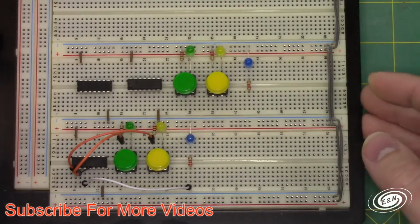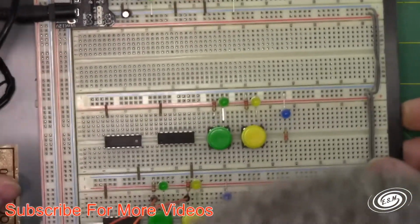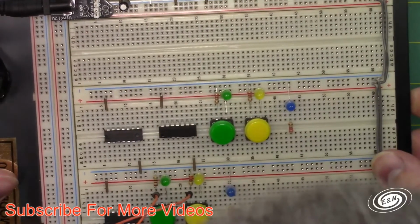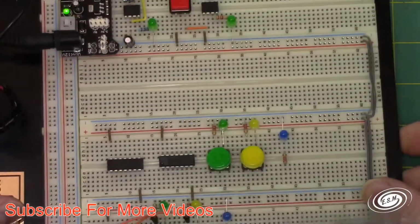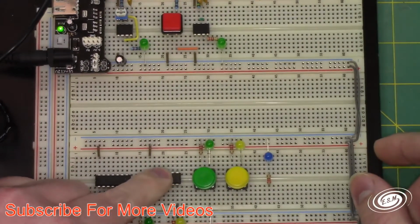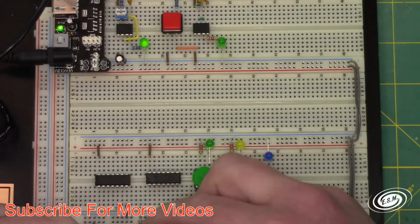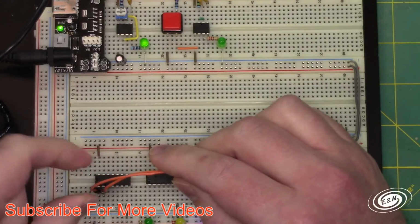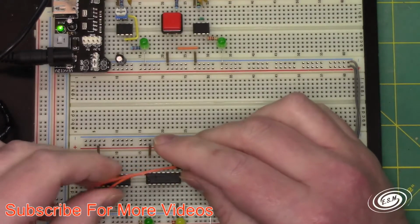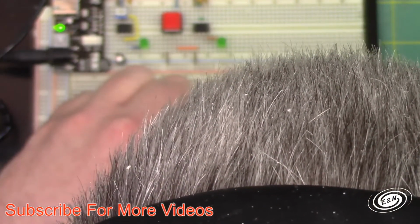Now up here, I did something a little different. I have an LS04 and an LS08. An 04 is an inverter. So what I'm going to do is come in here with my inputs, and I'm going to do the same thing. I'm going to plug that into that one, tying it low.